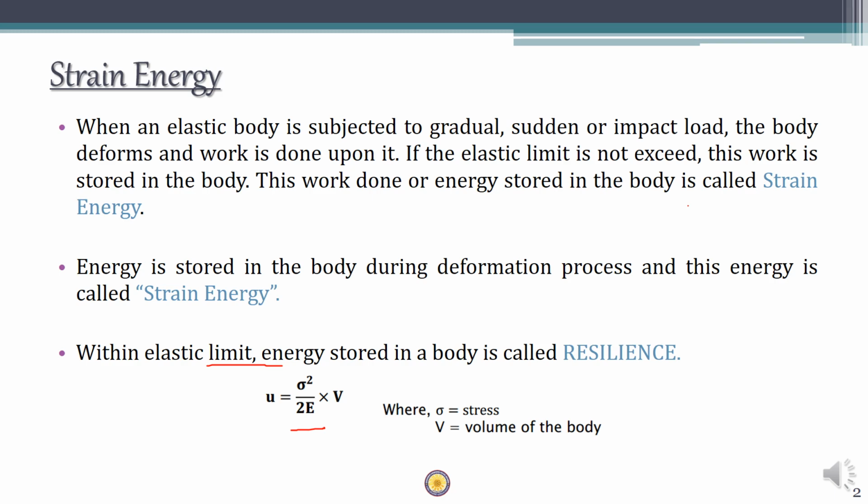But at this point it is worth noticing what our stress was. Usually we make a mistake while defining stress. We usually say stress is force per unit area, but actually stress is the restoring force divided by the area of the cross section. So the term restoring force R, or resisting force R, is important.